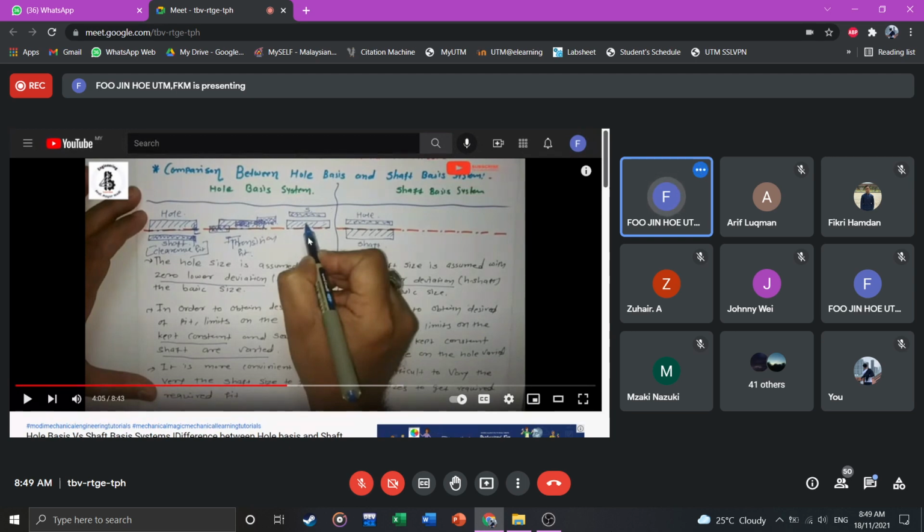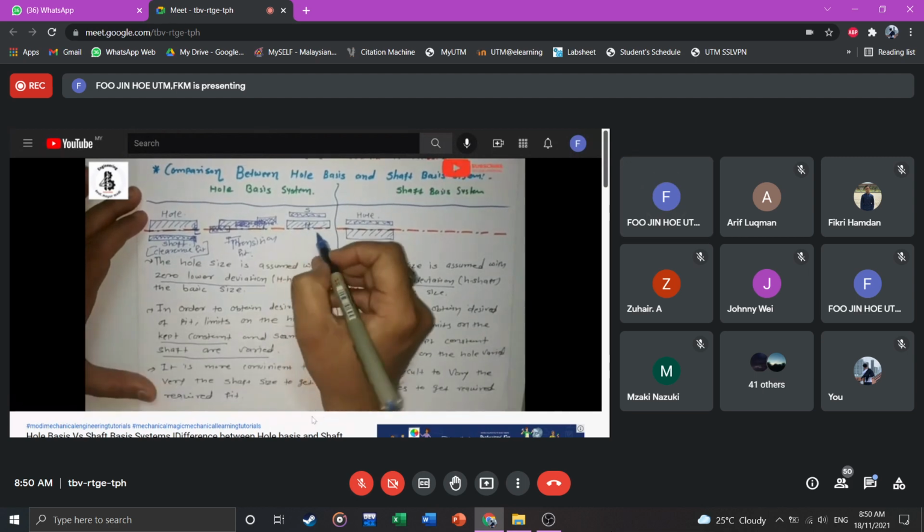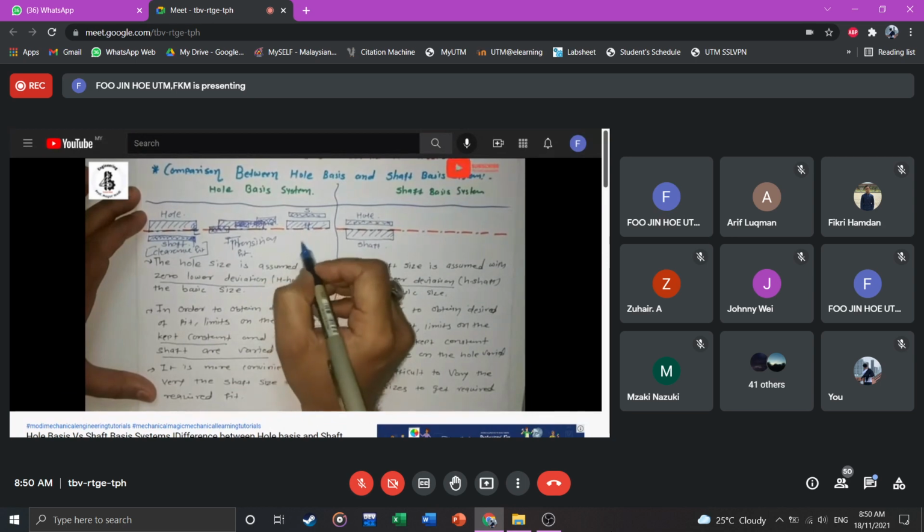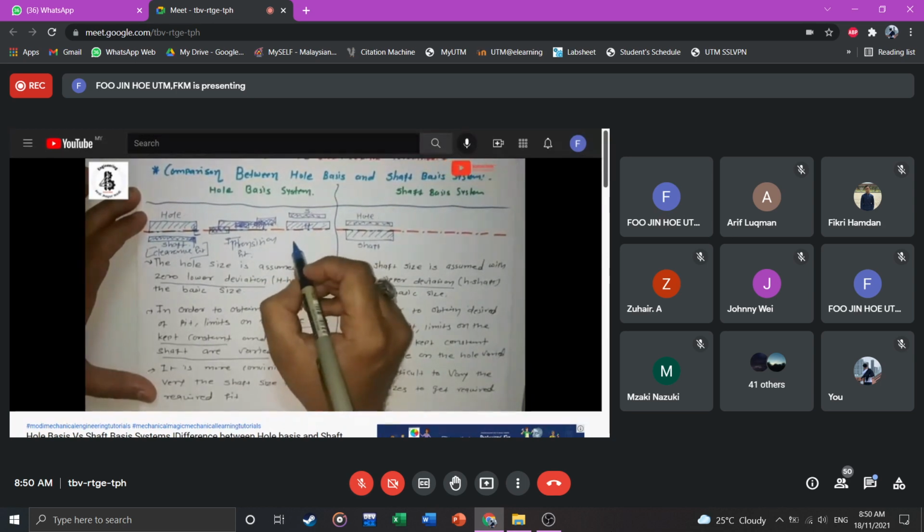So for the third one, currently as he has drawn it, this one is always tight, because no matter how you look at it, the minimum shaft size and the maximum shaft size are both bigger than the hole. So you can find such an alignment of the A and B components for the assembly.